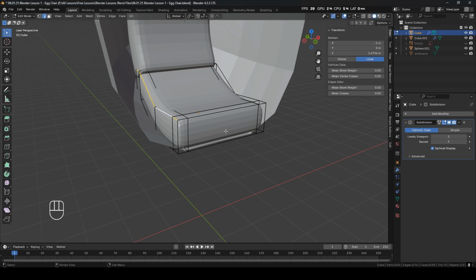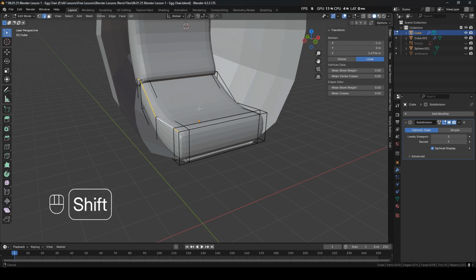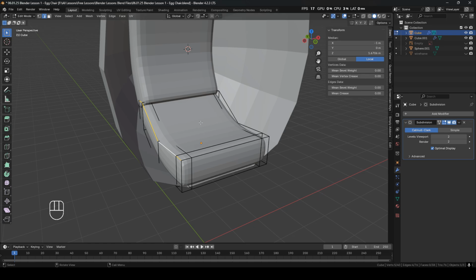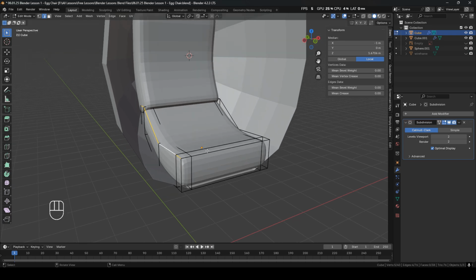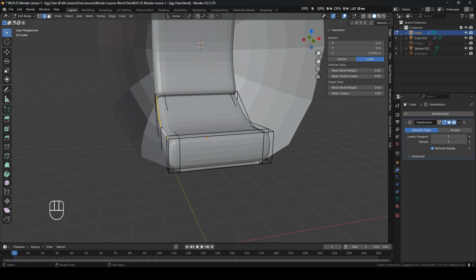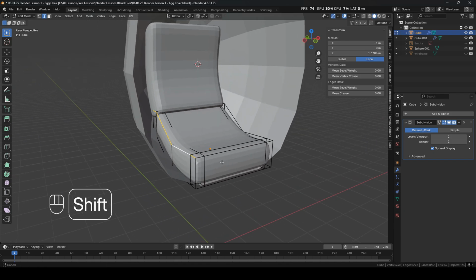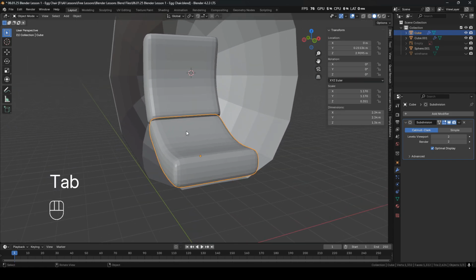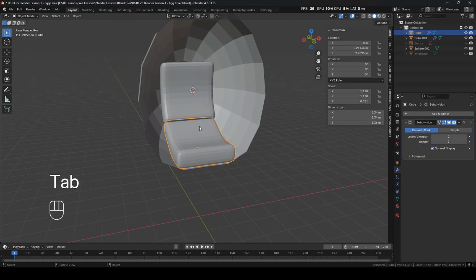This is how you would mark your seams, and a good example of marking your seams, if you imagine a cereal box and you think of flat packing your cereal box and opening it up, that's basically what the seams would do. It's the cut line, like a box, and if you picture it in your head of it flipping open and having it flat in a 2D image, that's how you put 2D images onto 3D objects. So I'll go more into that in a later lesson, but for now we are going to leave it like that.